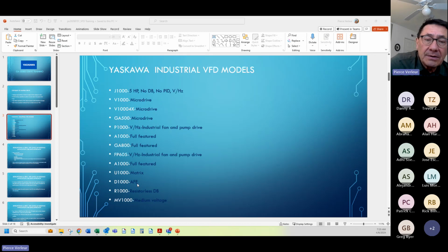When you require an active front end pointed at the power line to keep your power factor up and reduce your distortion to less than 5%, this doubles the cost of the drive, and it's where everybody else in the marketplace is in terms of harmonic compliant product.